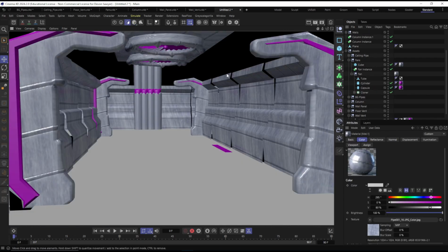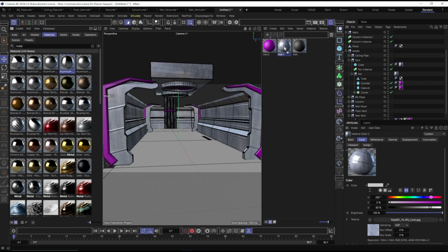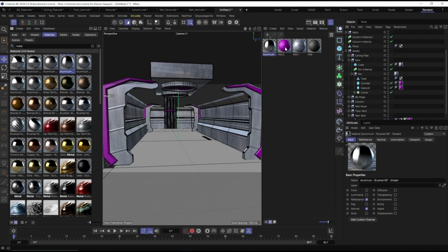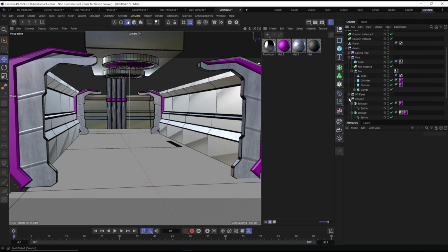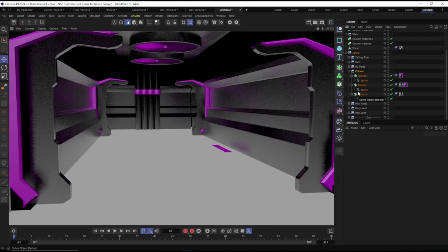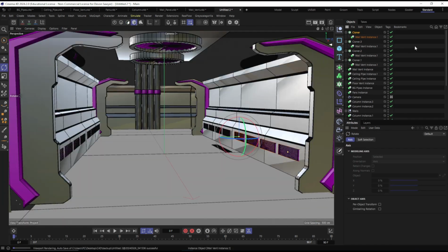As you can see, I wasn't happy with how the material looked once rendered. To replace it, I navigated to the Asset browser at the top left of my screen, then searched for a metal material. Once I found one I was happy with, I added it to my Material Manager, then began replacing it on each of my objects. Here's what my scene looked like afterwards. Continue the final touches on your asset placement.